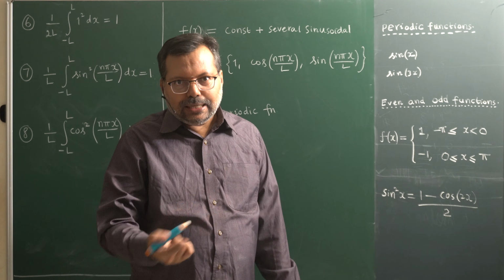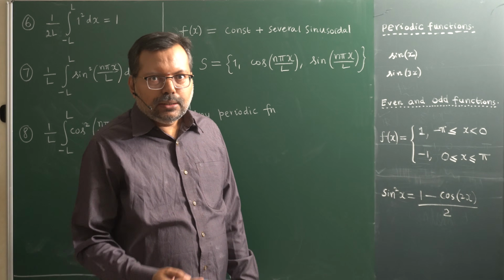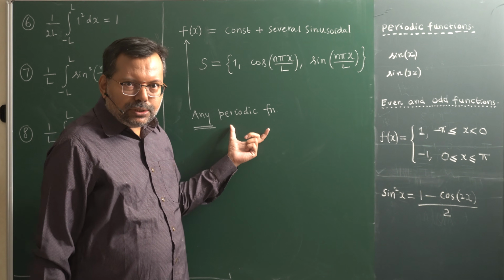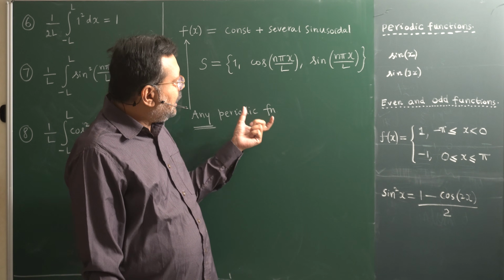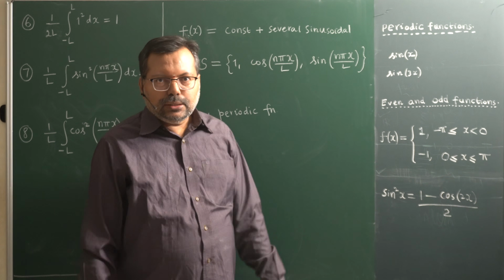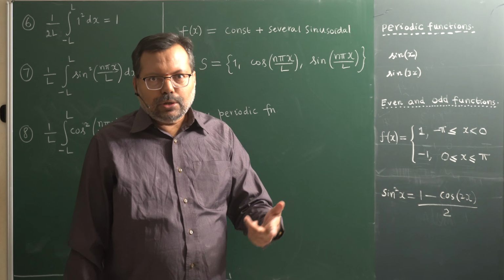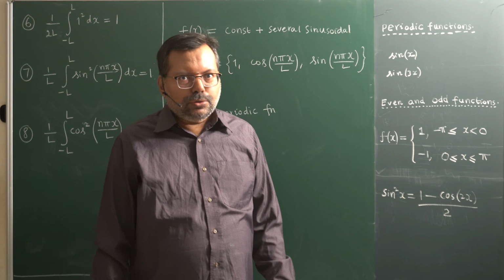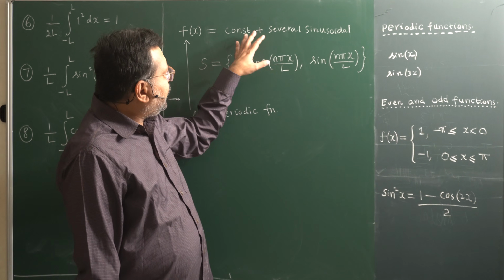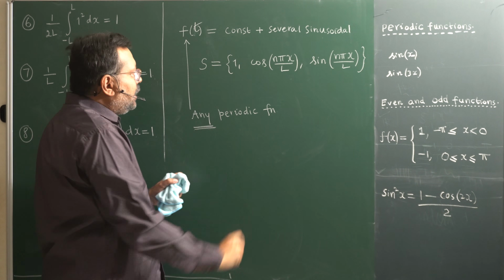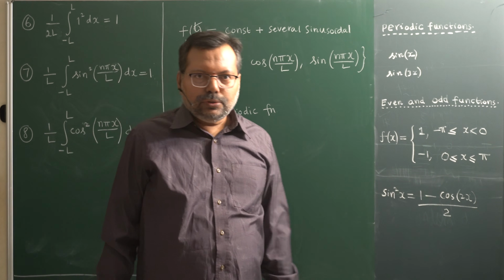That is called a spectrum analyzer. A spectrum analyzer means the system will analyze what this periodic function is all about, and it will tell you how many cos and how many sine waves are there, with what frequencies. In a practical situation, you will have a time signal, and this time will be converted to frequency.